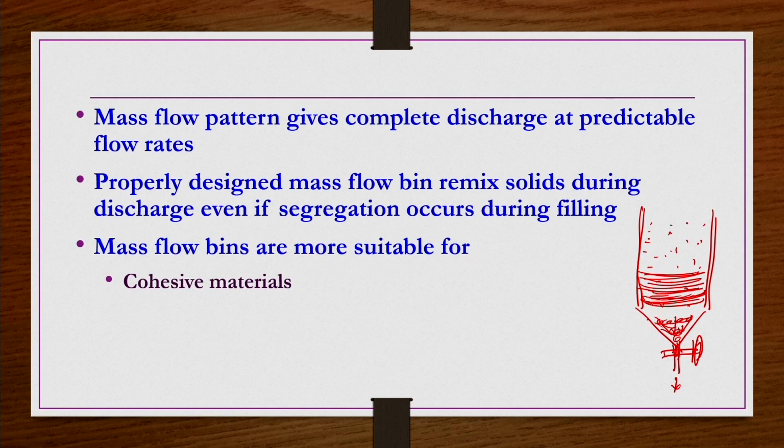So if you have bins where mass flow can be ensured, then such cohesive, sticky material may be taken inside those bins, so that we can avoid this bridging effect, and then one can have an undisturbed flow of the solids to the subsequent operations. They are also good for materials which degrade with time. We are going to see other kinds of materials.